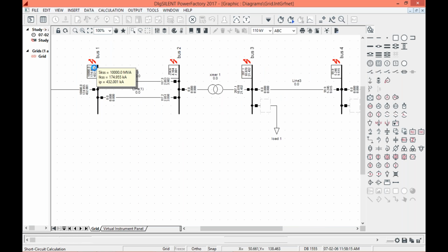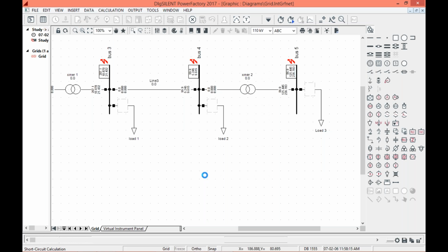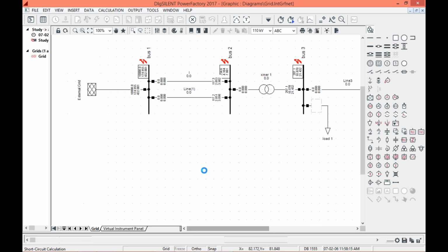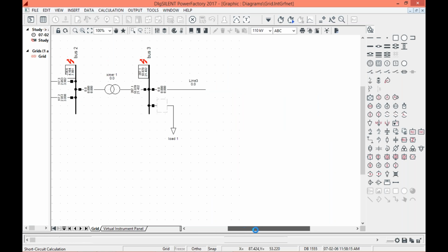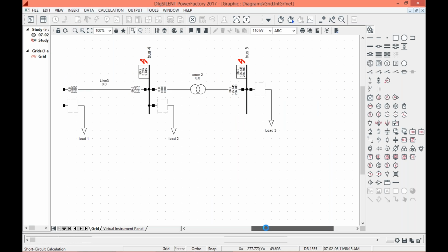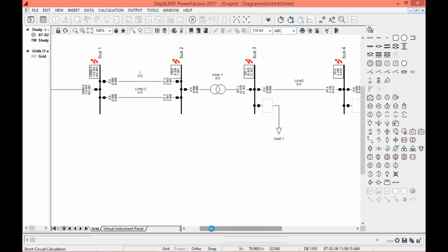As we see, the short circuit runs accurately and it is showing the various MVAs, ampere values and all those things for every single bus. So accordingly, we can determine which bus is out of control. The control manager could work upon them and decide what the process is and how we are going to control our network. There are various options available in the short circuit analysis, so you can choose according to your need what you want to do with this.